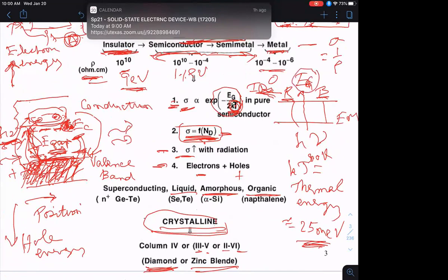And remember, I said that if my band gap is over here, it would absorb these higher energy photons, but transmit these photons, right? So here, if I'm looking at these ternary and quaternary semiconductors and I engineer the band gap, what's going to happen to the color of the semiconductors? It'll change, right? So you can engineer the minimum photon energy that you can absorb.